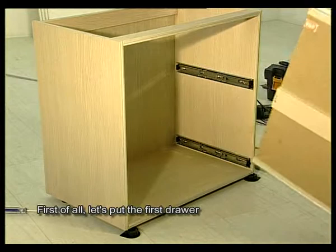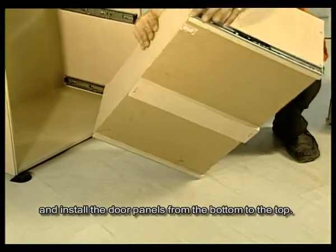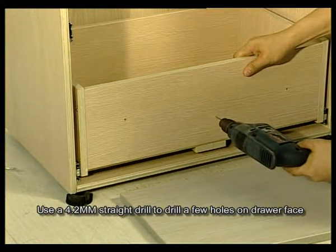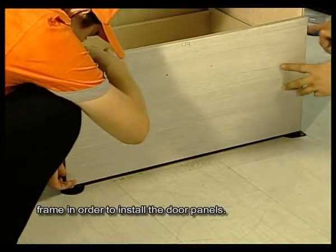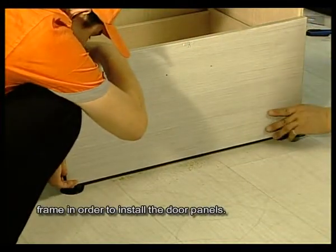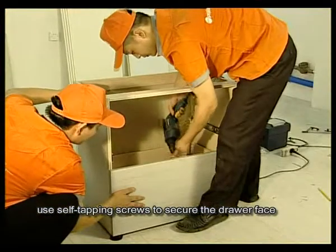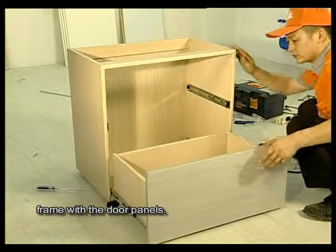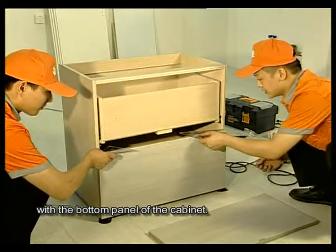First of all, let's put the first drawer on the slides of the cabinet body and install the door panels from the bottom to the top. Use a 4.2 mm straight drill to drill a few holes on the drawer face frame in order to install the door panels. After drilling the holes, use self-tapping screws to secure the drawer face frame with the door panels. The bottom of the door panel should be level with the bottom panel of the cabinet.